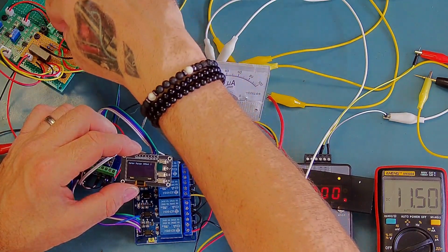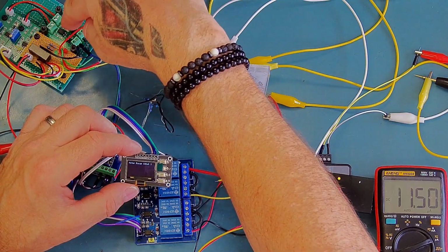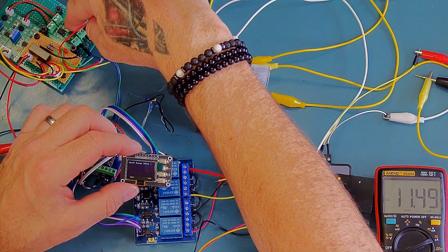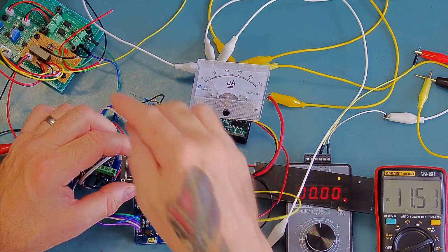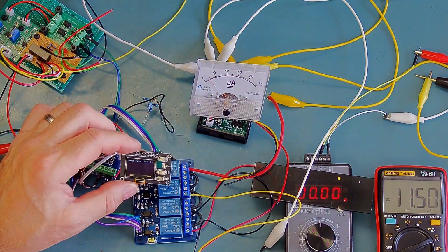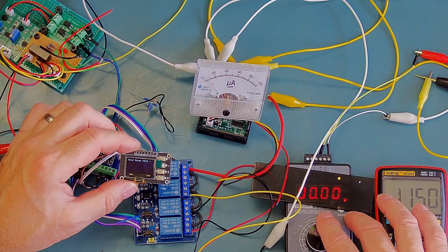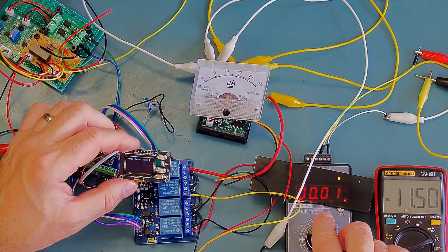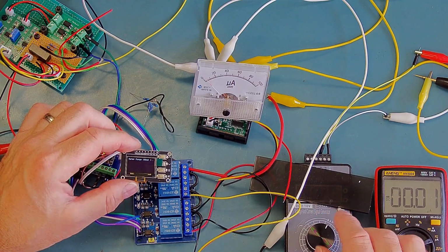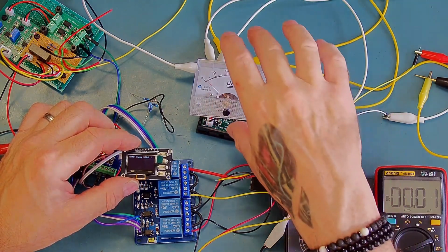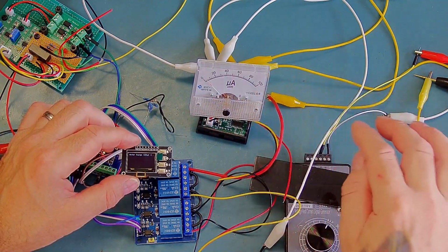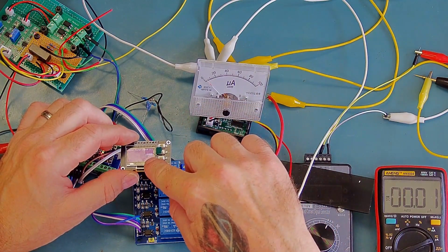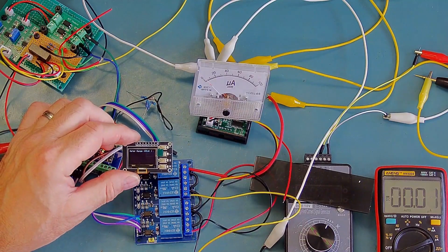Okay, so hopefully you can see the LEDs that will be on the opto-isolators here. The one on the bottom here is for the under range, and the one on the top is over range. The only way I can get the under range to go on is actually to switch this meter off. Okay, now we can see that the meter's gone pretty much to 0, and you can see on the display here, hopefully you can read that, it says under.